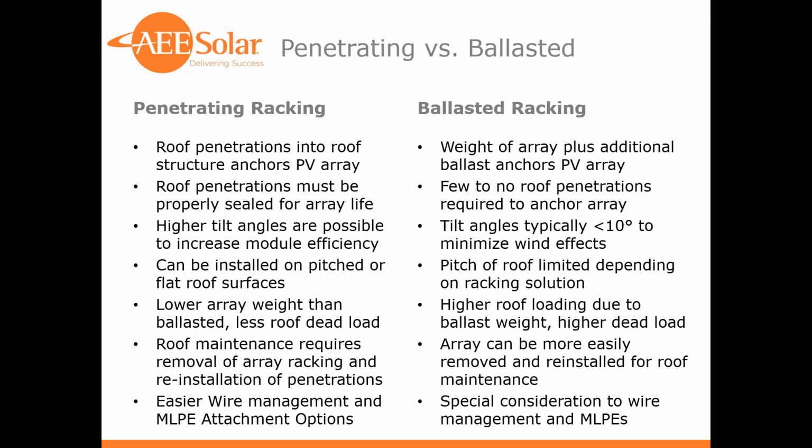On a penetrating racking, it's a pain to service the roof. I mean, you've got to remove the racking, the anchors, everything, get down to the structure, potentially to service that. Pay for the array to be removed, stored somewhere, and then basically you're reinstalling the array. On a ballasted racking system, we can easily service a small portion of the array without removing it entirely.